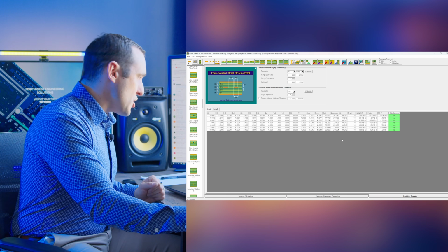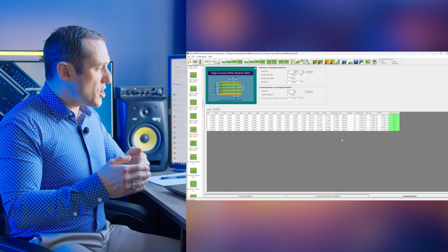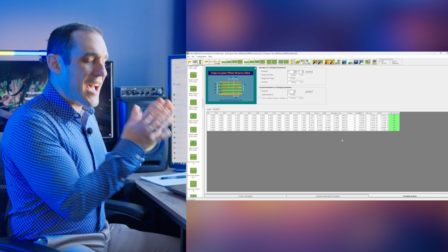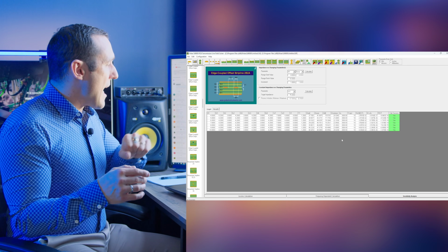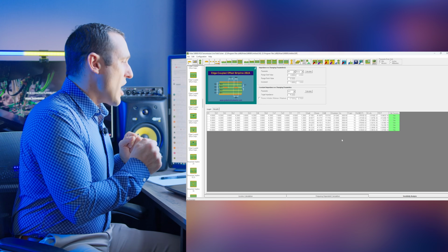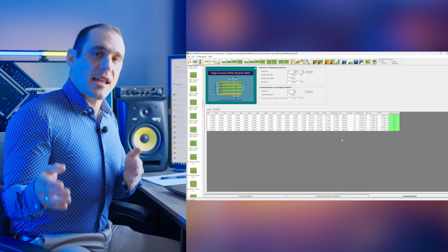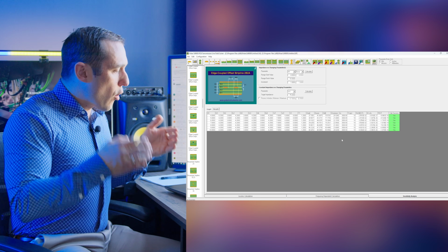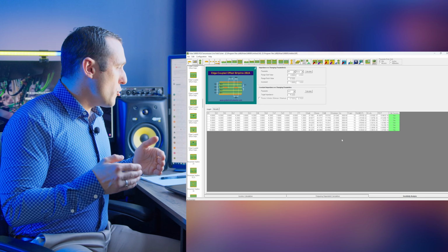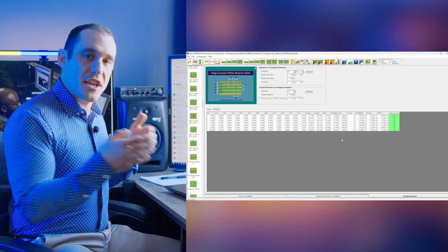So this is really nice. It shows me just how much variation in the impedance of one of these traces I could expect if we had our substrate thickness changing from 4 mil to 10 mil. That's really useful for analyzing things like manufacturing tolerances or what would happen if you were to swap out some materials in your stackup.